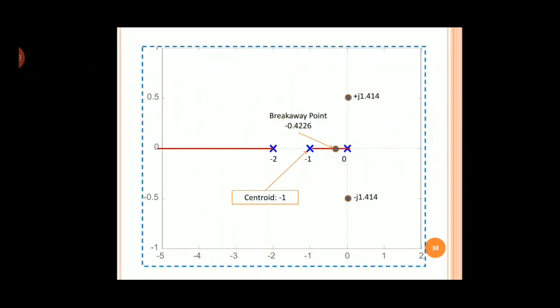Now we are coming almost towards the end; we are left with one more step that we will see later. So far from the previous steps, we identified poles and zeros and the number of branches. Whatever information we have got from the previous steps, mark it on the S plane.